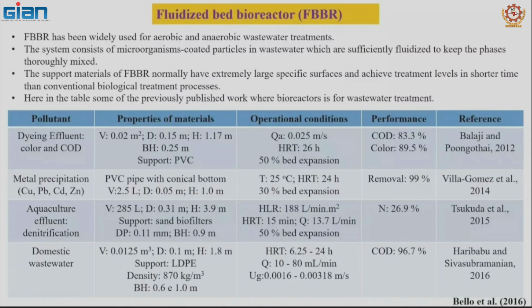These bioparticles are sufficiently fluidized to keep the phases thoroughly mixed. So intimate contact between the liquid phase and the solid phase, that is bioparticles, is possible. We get a very high mass transfer and reaction, that is degradation of the contaminant.